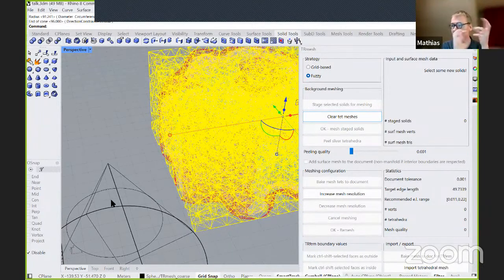And nTop has all these intricate gyroids. And how do they modify them? How do they model with them? Well, they represent shapes basically as the zeros of functions, and then they modify the function, right? So I think that's the best answer to that question. The scalar field just represents the values of that function in the sense of the frep that nTop uses, if that makes sense.